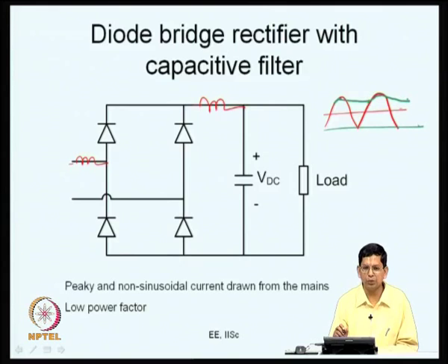So, you reduce the ripple to an acceptable level, and you put a big enough capacitance effectively to realize this. In fact, the capacitance sizing can really be done by this. You have to look at the load current and the time between two charging intervals for this load current, and the product of the two gives you the extent of discharging of the capacitor.